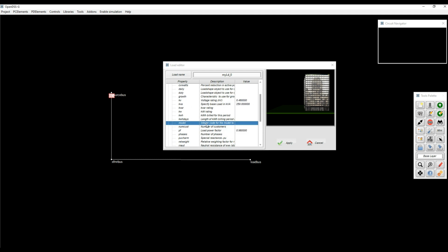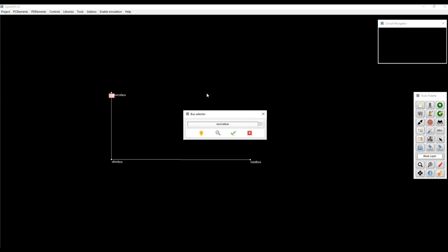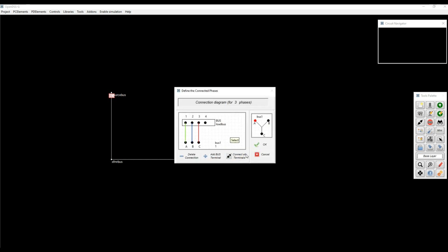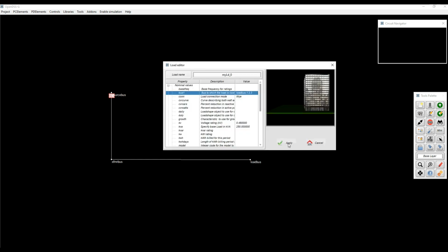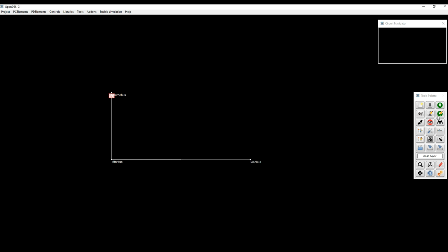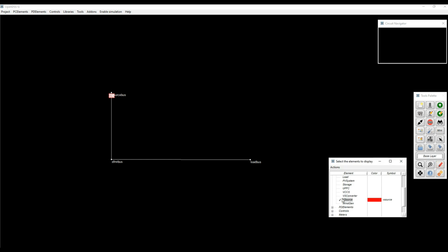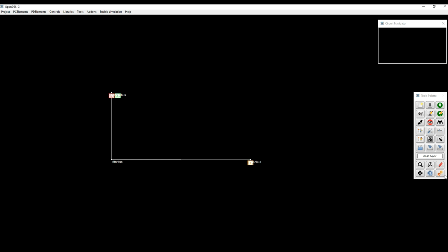It's telling us, hey, there's a problem. You didn't define the bus. So that's another interesting feature here. We're trying to detect or secure the needed values, the mandatory values, before we apply them on the element. So we can now again try to edit the element and we'll be fine. So we can see now through the element manager where is the load and where is the transformer connected in the circuit. Now, since this is a new model, we have to save it before we can proceed.